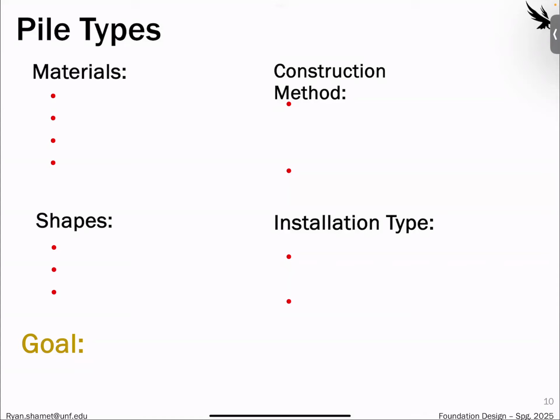So this project's very specific with the contractor SGL and what they wanted to do, but hopefully you saw some of the trends where a lot of these steel pipe piles were driven in marshy areas or through the lakes. And then a lot of the concrete piles were driven through sand and through dense areas. So we'll talk about that, but the mechanism of friction, the general rule of thumb is if you have a